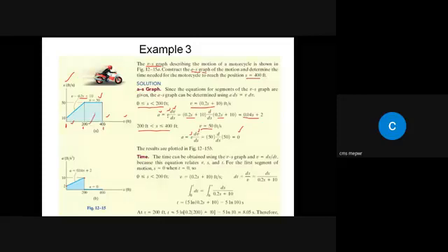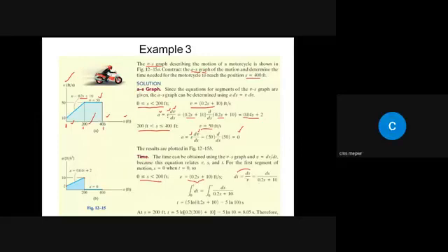So let's do it, the time from here, 0 to 200 feet, and v is equal to this equation. And as we know, velocity is equal to ds by dt, right? Yes, sir. So dt will be ds by v, and for v we will put this value. Take its integral, and the integral will be from time t is equal to 0 up till t, and the displacement is from 0 to s. In this case s will be up to 200.